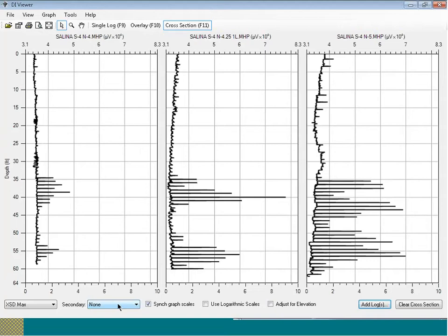This is a much more permeable area, coarser grain materials, and we went down with the HPT groundwater sampler and collected samples where we suspected to have no detections, non-detect locations, as well as higher responses. So we have a fairly good profile of these logs with the lab analytical data.